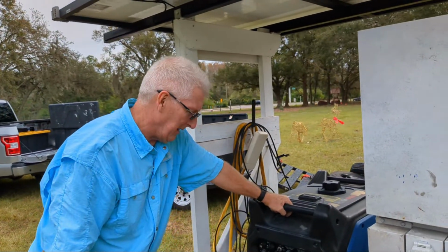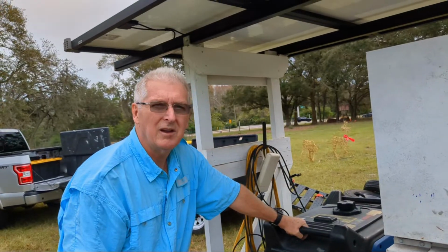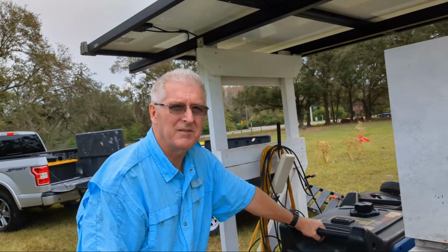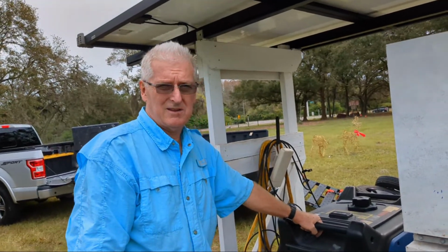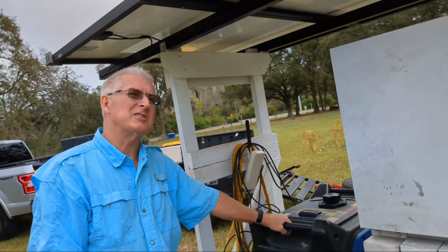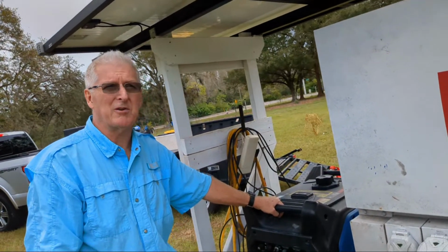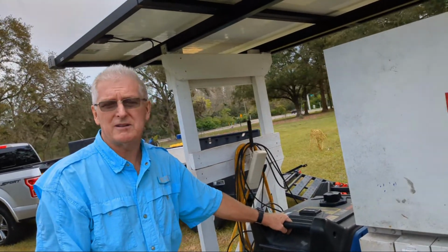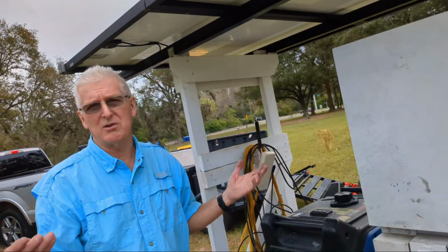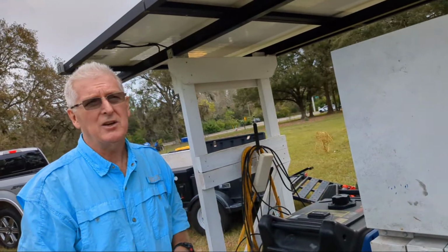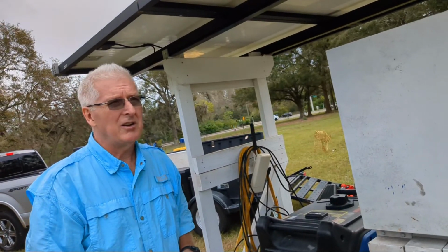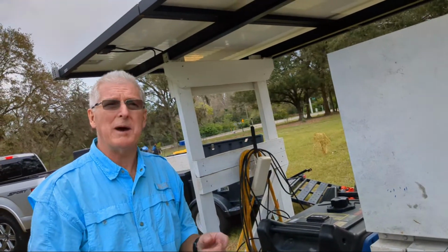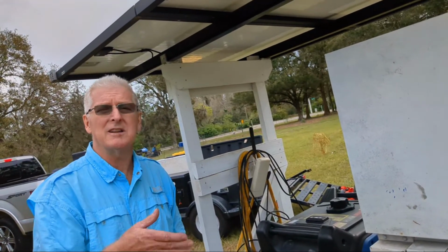And you're saying the trucks normally, even though they have rubber tires and they're not grounded, have a negative polarity for the whole truck. That's right. And that creates a sort of pseudo ground? Well, no, it's just that it's impossible to create a ground for the truck, so they don't attempt to do it. It would be called a local ground. The local ground would be the chassis, which actually has electrical potential, the potential of the battery, because the chassis is bonded to the negative terminal.